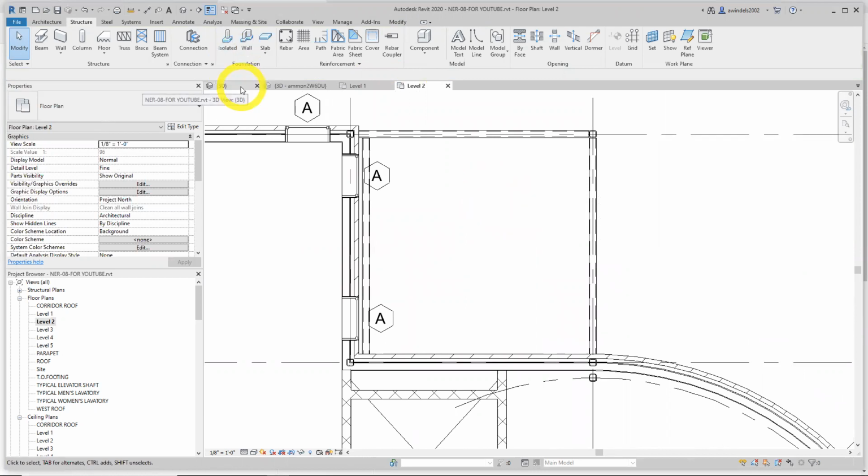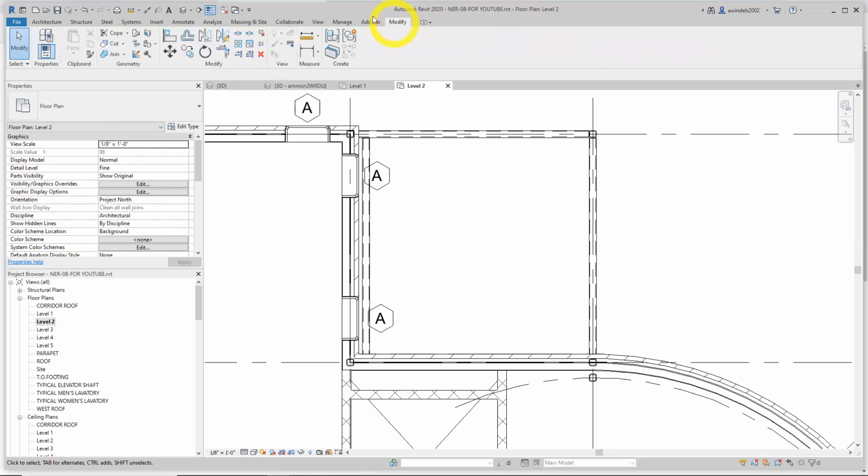Let's add a beam system now. If you draw your framing to and from beam center line, Revit won't always keep your connection points. Sometimes you have to trim, and it'll trim the beam back for you. We'll get into this at another time maybe, but there's a Beam/Column Joins tool in the Geometry panel of the Modify tab, which is right here.